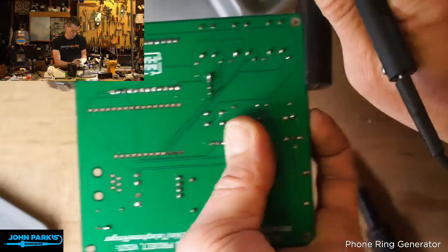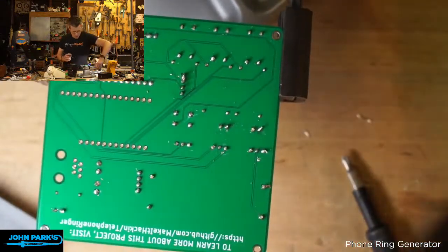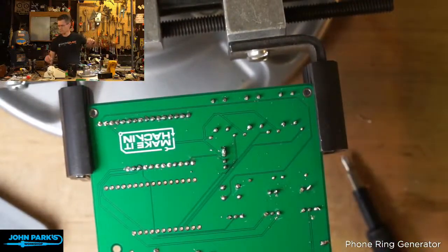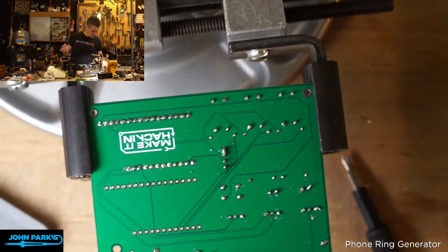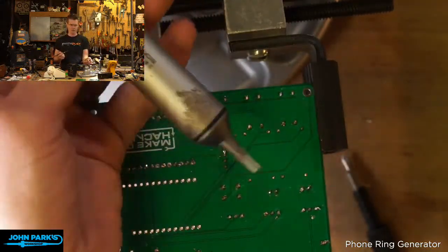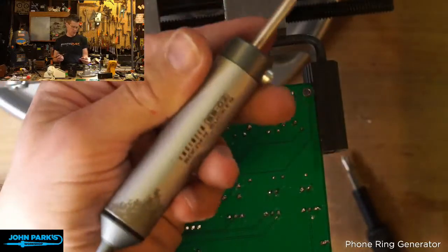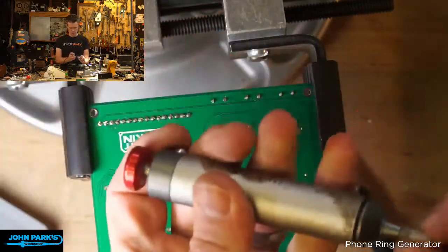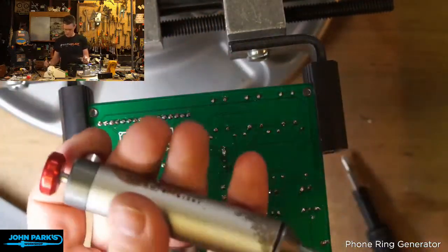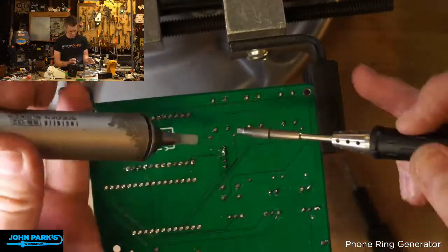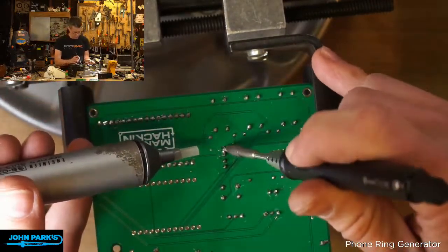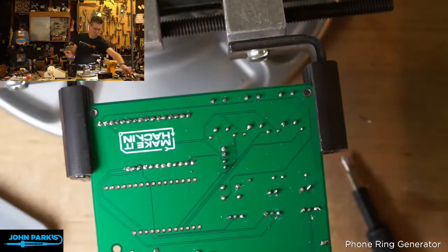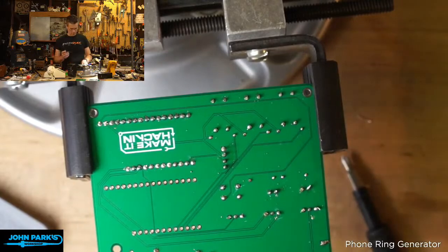And what I'll do is go in and suck this solder away from here. A wick would be good too if you have that. Here's a solder sucker. This is a really good one. I've had this one for many years now, but it's an Adafruit sold Engineer brand, which is a great brand of stuff. You can get it other places too, but love this solder sucker. It has these little silicone tips, so it doesn't melt like some plastic tips, but it gets a good suction. There we go. So I will resolder that point, but that means I've no longer got that bridge right there.